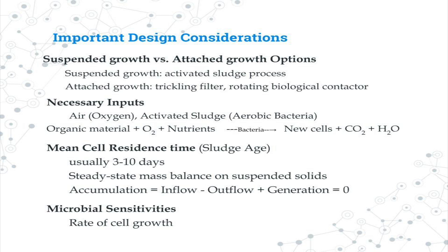In order to keep the microbial sensitivities, minimum organic concentration is required. When the concentration decreases below the minimum value, the growth rate becomes negative, making the process less efficient. The growth rate can be estimated as the rate of production of volatile suspended solids.